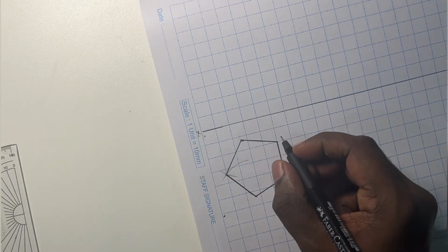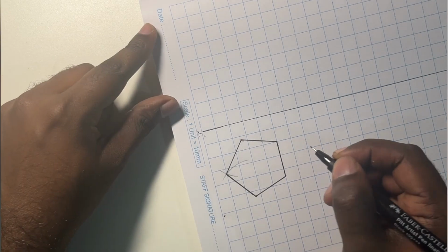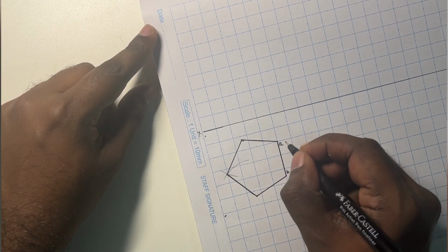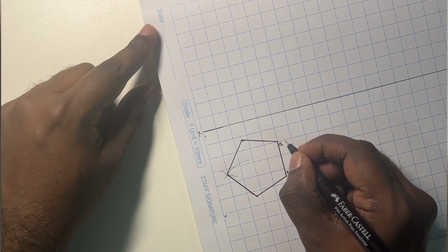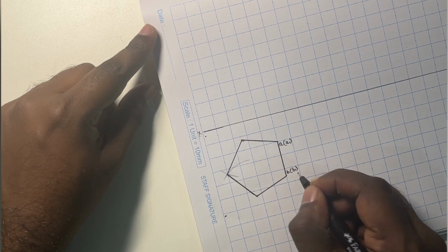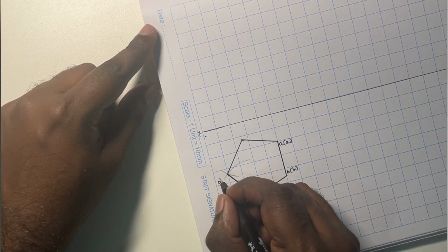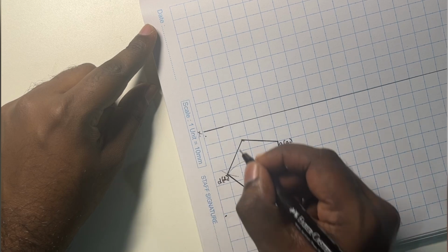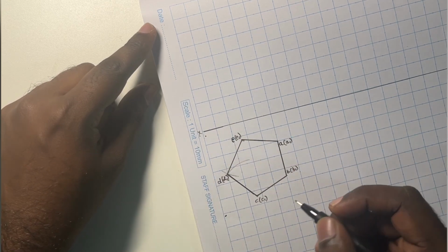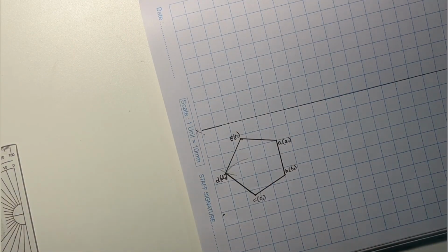So let us tell that it is resting on one of its base corners A1, B1. So A1, B1 will be the bottom face, which is not seen. So AB will be the base edge of the top face of the prism, and this is A1, B1 inside the bracket. Similarly, C, C1, and next D, D1, and E, E1. So the checkpoint here is I've considered the edge towards the right hand side, which is very important.